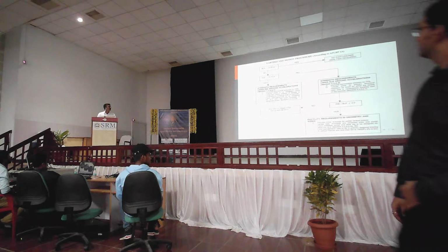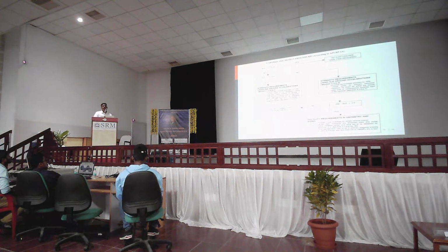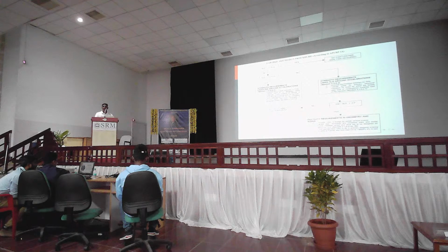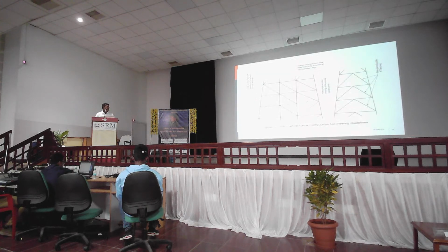So you can see here, even for our SLE, strength level earthquake, the acceleration is very low, something like less than or equal to 0.05 g. We may not go for earthquake analysis itself because we have already designed our structure for lateral loads like wave, wind and all. But if it is more than 0.05 g, we need to go for a specific earthquake analysis. So guidelines are there in codes, we can follow.